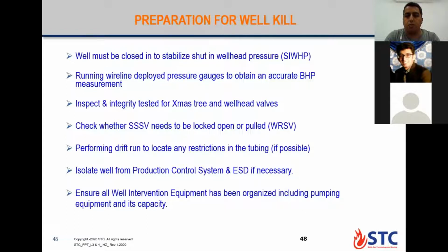Yes, you can close from the subsurface safety valve or close from the lower valve on the Christmas tree, but you need to replace the top valve. After you set the plug inside the wellbore, so you have two barriers, then you check its integrity, then you replace the top valve, like the crown valve or wing valve.